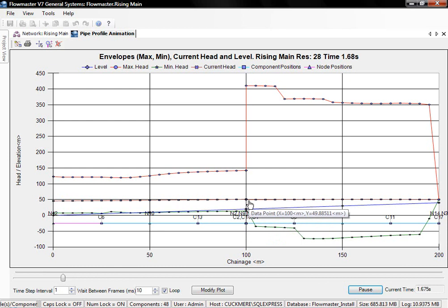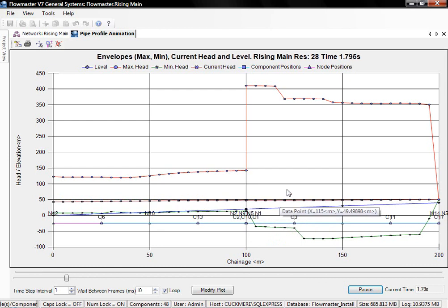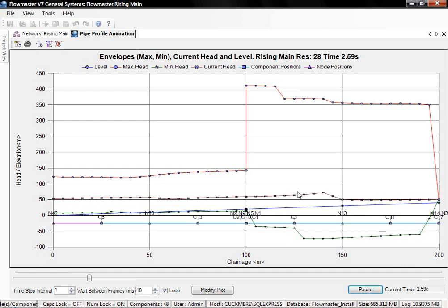So here we can now see a small amount of movement as the pump trips. We can now see a small pressure wave passing up and down the pipe caused by the check valve closing upstream of the pump. That will eventually be damped by the system. Now we are getting near to 5 seconds, at which point the valve will start to close.